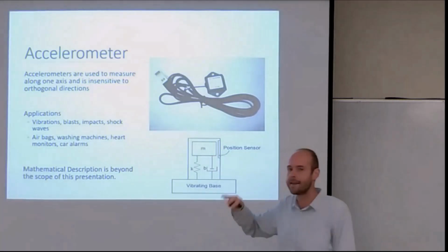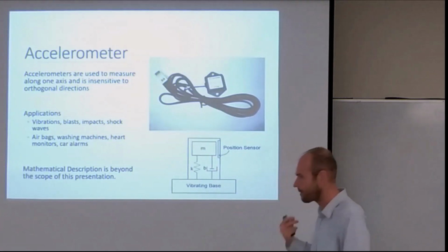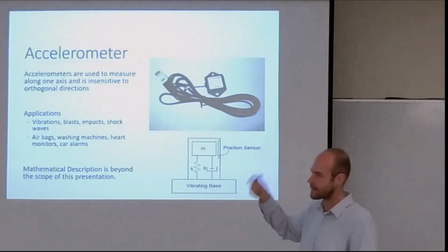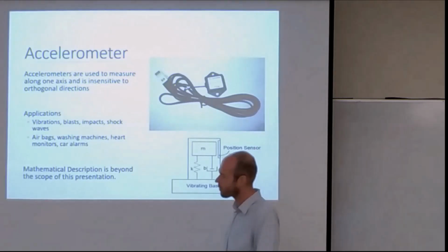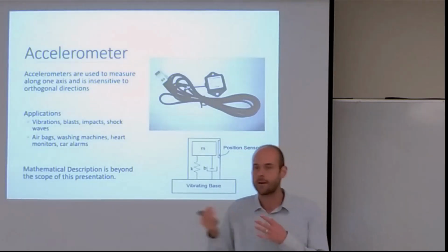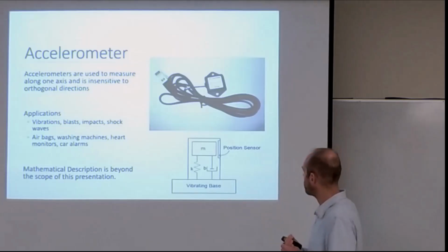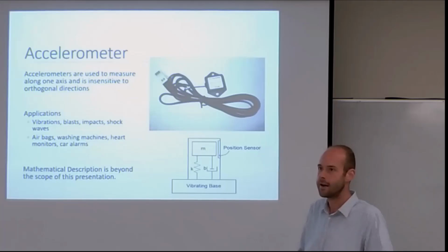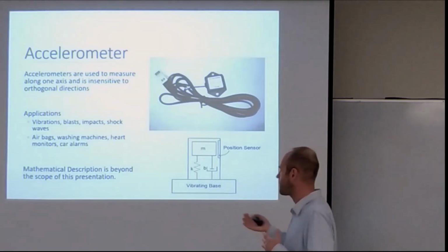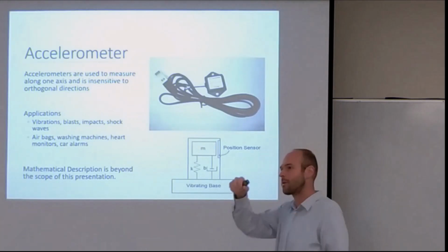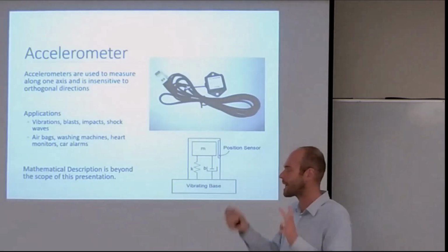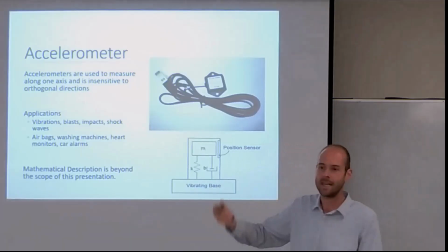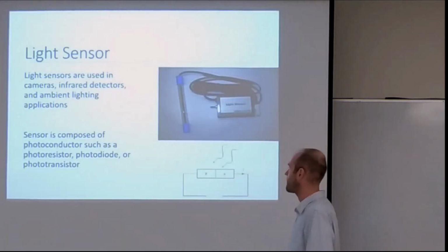Accelerometers are based on moving masses or bending cantilever beams. So you have some piezoelectric effect, meaning as the stress and strain changes, the resistance changes, and so you have a measurable quantity in the physical movement of a cantilever beam, for example. A gyroscope would be a more complex geometry. But as you turn your cell phone to the side, it knows to flip the screen because there's acceleration applied. And you can measure those physical happenings electrically and make choices based on that.